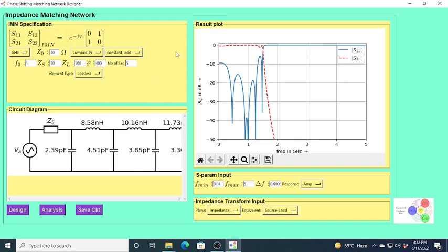So this can be adjusted. Here you have a certain peak which is more than 10 dB. So that can be decreased by changing this phase. So here I am basically utilizing the phase as the design variable instead of utilizing the exact phase, because one of the facts is that we basically want the phase difference, not the absolute phase.